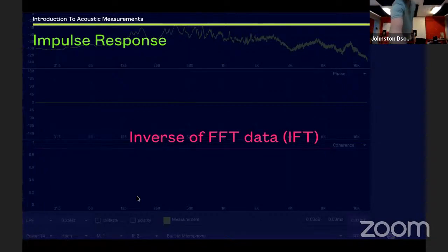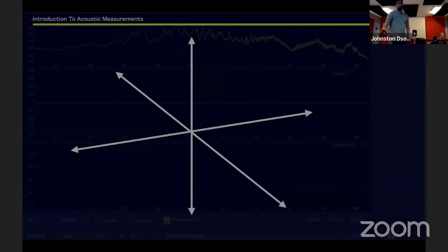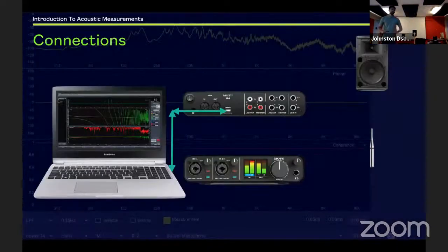So basically, the software loopback would not work because your sound card is going to take some time to process the data, from analog to digital and digital to analog. So that time taken also needs to be taken into consideration. If you do a direct loopback internally, that time is not going to match. So then you won't have a right reference. I hope that answers your question for whoever asked it. So you cannot use a software loopback. You will have to use a hardware loopback.